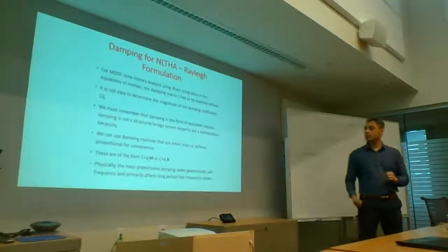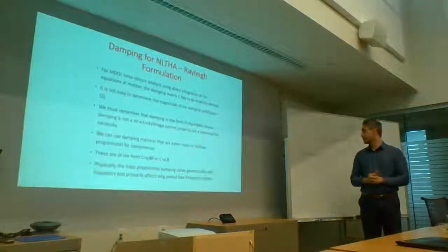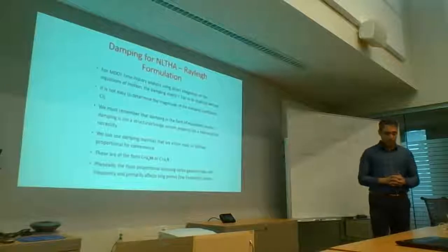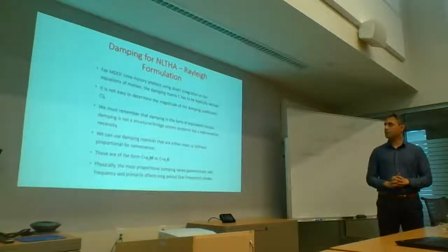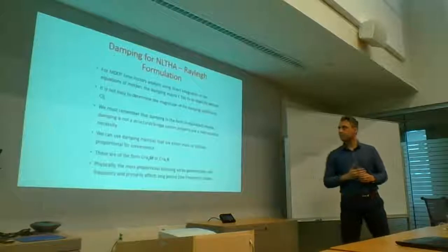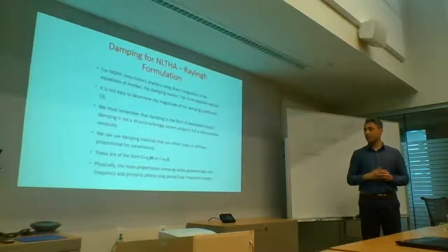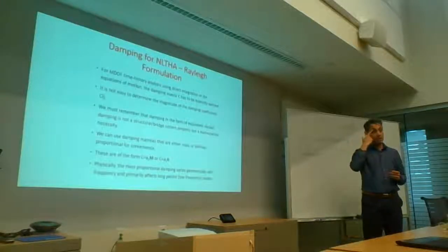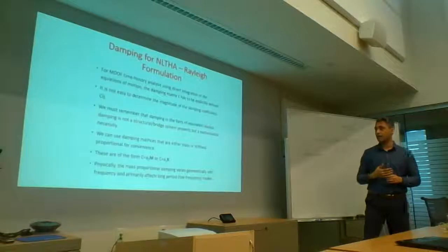Okay, so I want to talk a little bit about the damping formulation. There's still a lot of research being done on damping for nonlinear time history analysis. So when we're looking at multi-degree of freedom time history analysis, and we look at direct integration, our damping matrix C has to be explicitly defined, and it's not easy to get those damping coefficients.